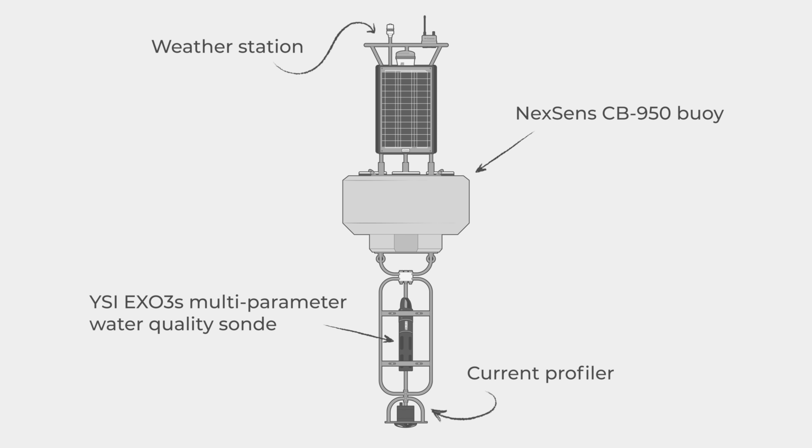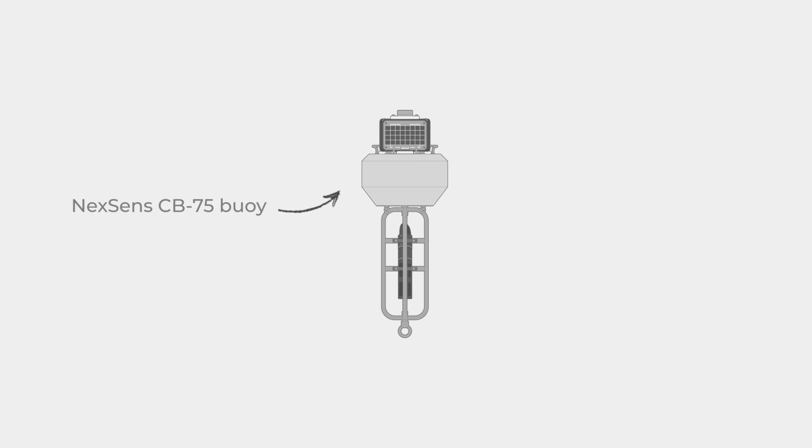In lower traffic environments where visibility and the above water profile of the buoy aren't a concern, you could also scale down the system to a smaller buoy, but be sure to check project requirements and power budget, as the battery life may limit the frequency of data transmissions. For today though, we'll go with the XB-200, since it offers more potential to scale up instrumentation in the future.